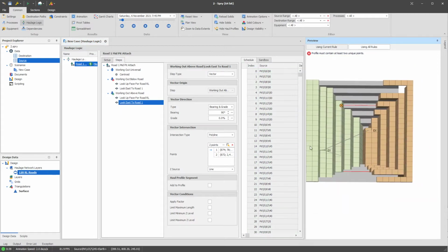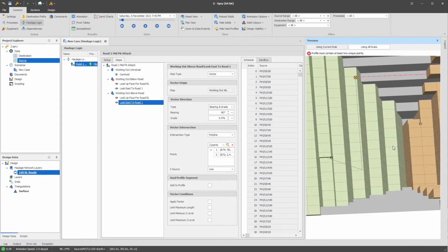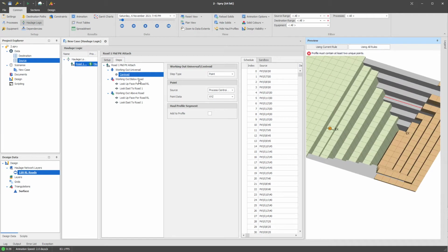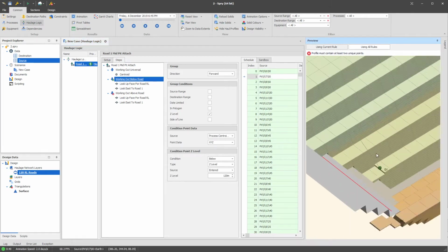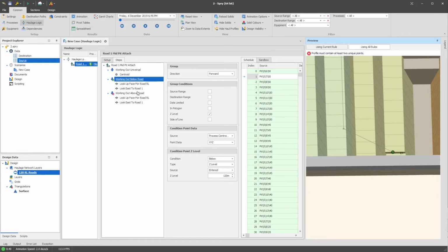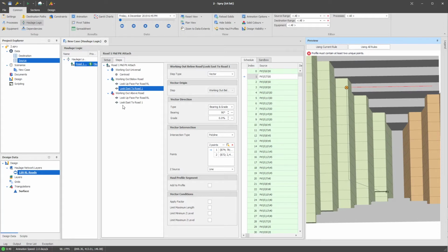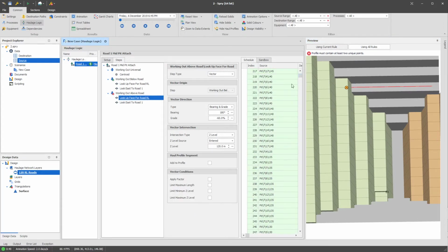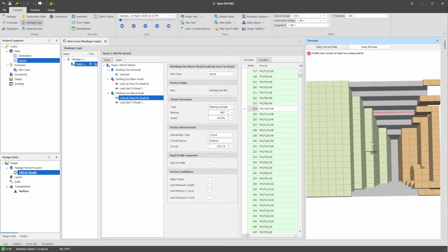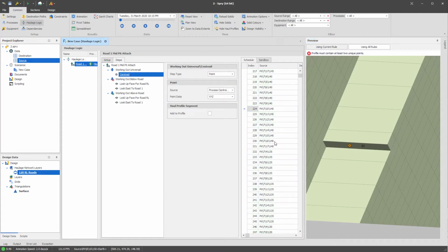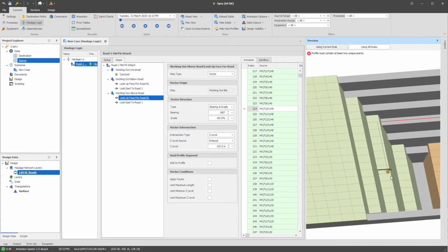This grey line that's cutting across here, that's tricking me a little bit, this is called the source destination line. So that's where the destination is for this particular record. Okay, so to summarize, we've started at the centroid. If we are below the road, as we are in this example, we look up the face at the dig angle of 60%, and then we look across to the road at the angle that the road is at. If we are above that road, then we look down the face towards the road, and then we come back across.